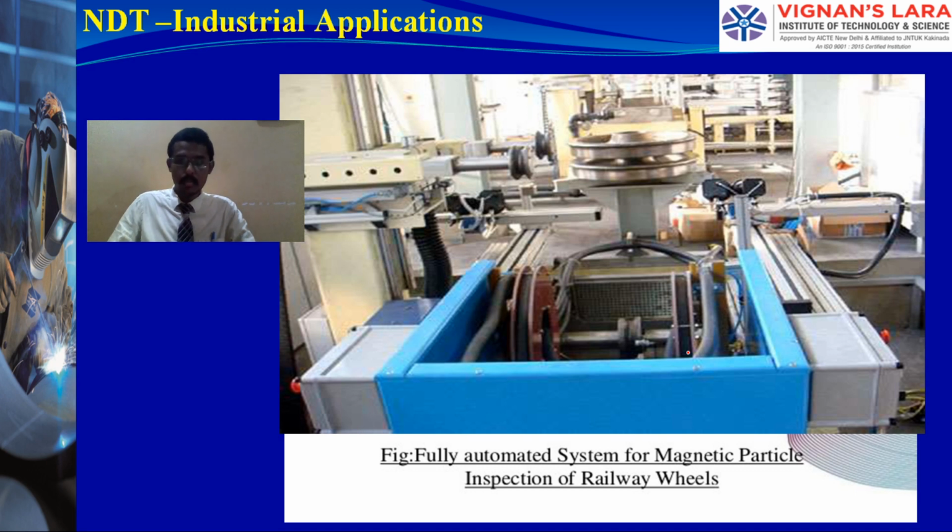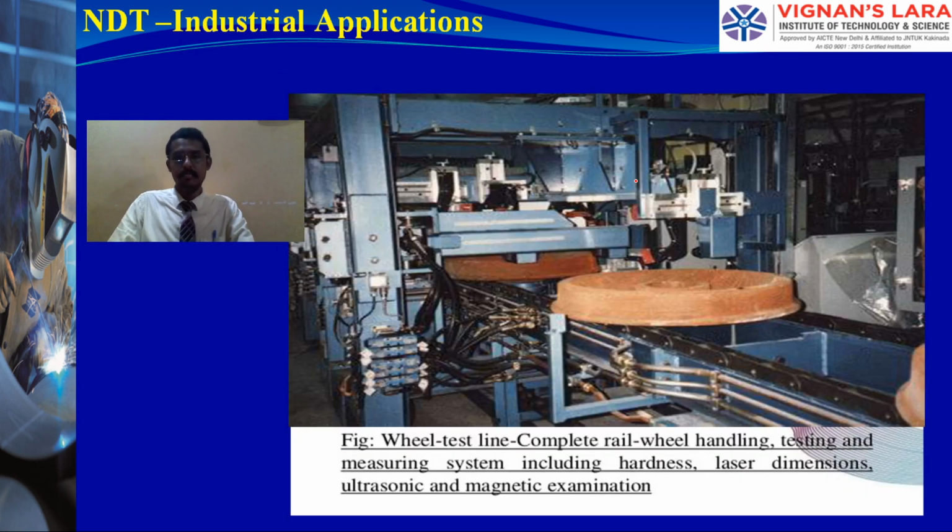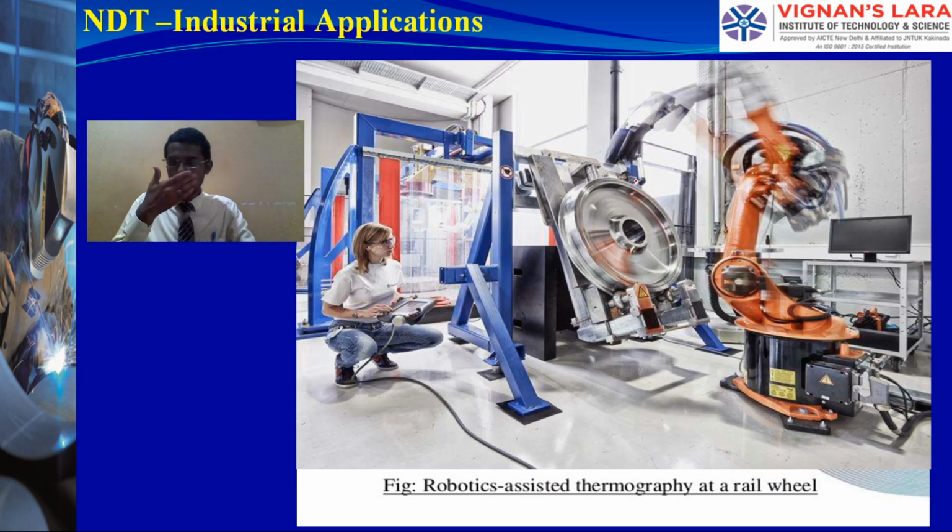So of the few, this is magnetic particle testing, automated magnetic particle inspection of the components, a similar testing process. Here we have seen multiple techniques: magnetic particle, radiography, ultrasonic, eddy current. At the last we have seen thermographic inspections also. Vibrothermography, pulsed thermography, and lock-in thermography are some of the techniques we can use. Any one of these techniques can identify subsurface and surface cracks.